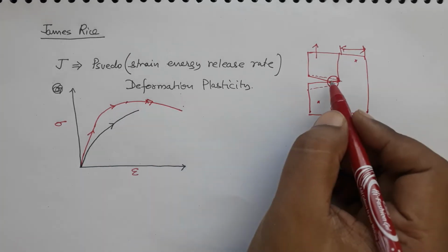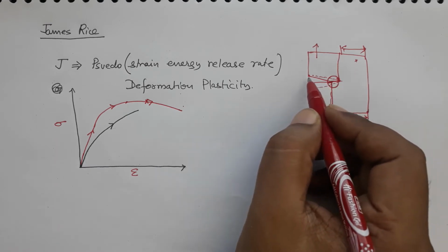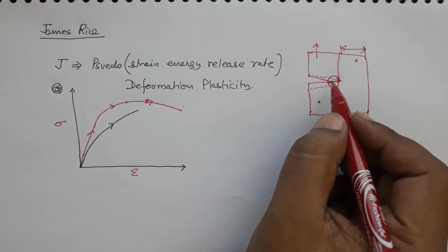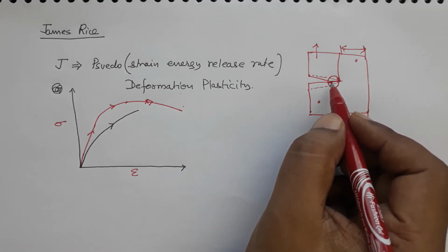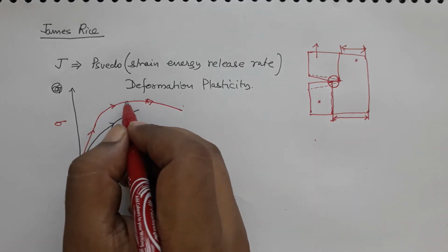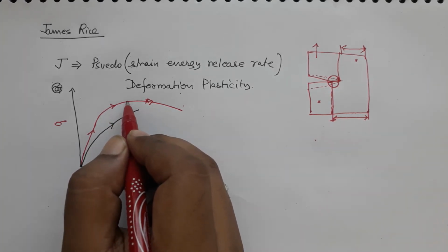So, obviously, you have some amount of plasticity at the crack tip before the crack would grow, and once it has grown, this area which was before at the crack tip, but now it is free of surface, has plastically deformed. So, we are somewhere in the plastic region, right. And then it has become stress free. So, it means it has unloaded.